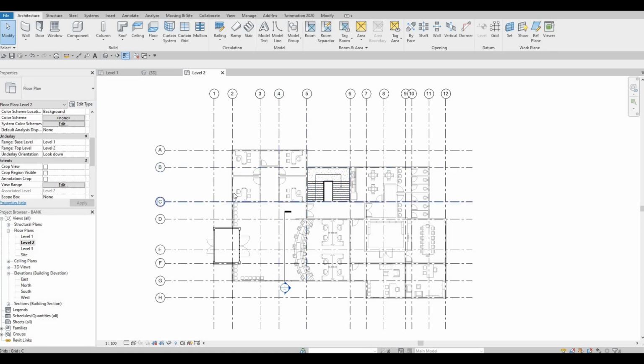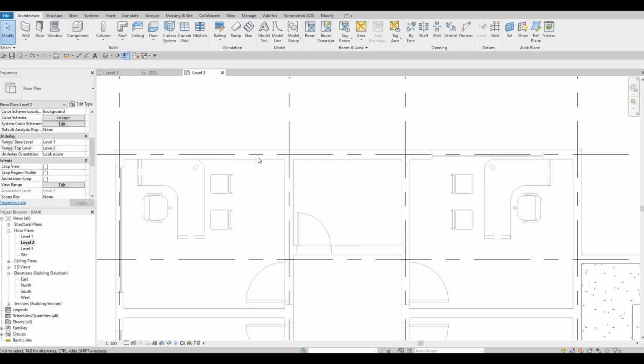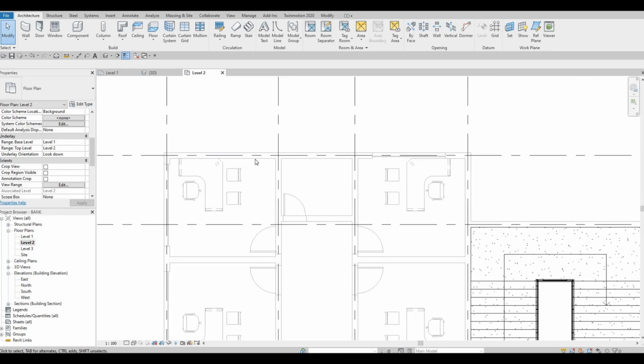So now what I want to do is add exterior wall on our level 2. Here I want to be able to select whatever's down there. So what you need to do is uncheck this one, select underlay level. Once you do, you'll be able to select anything that is under your underlay. So you want to make sure that this is all checked. This one is face by element by face, so make sure to uncheck that as well. You want to make sure that everything is able to